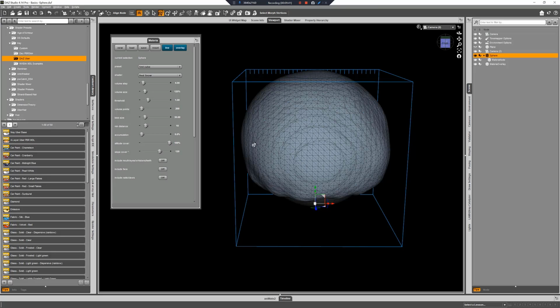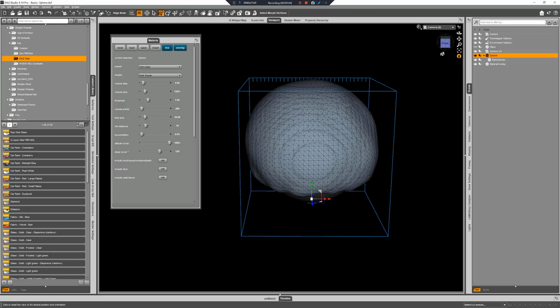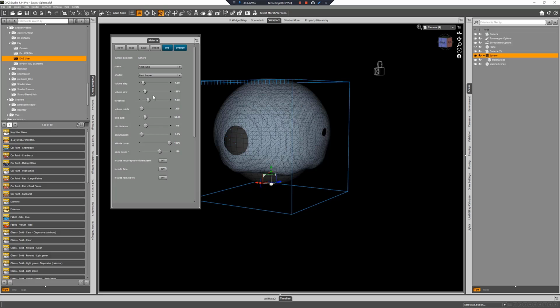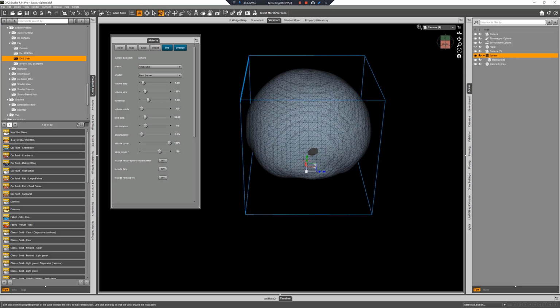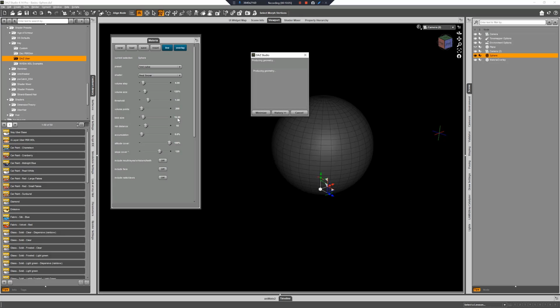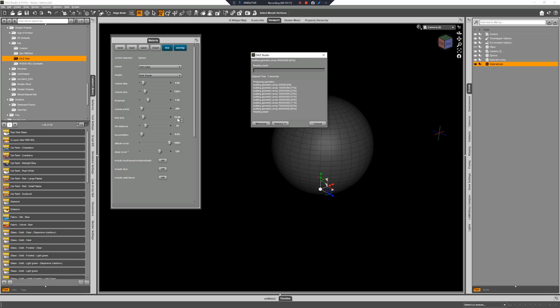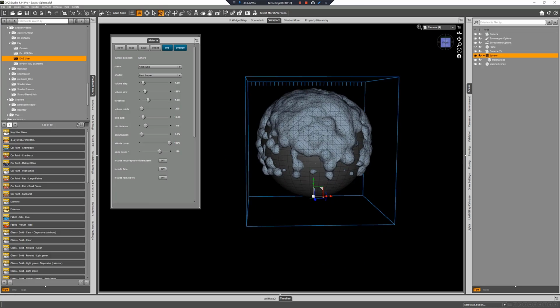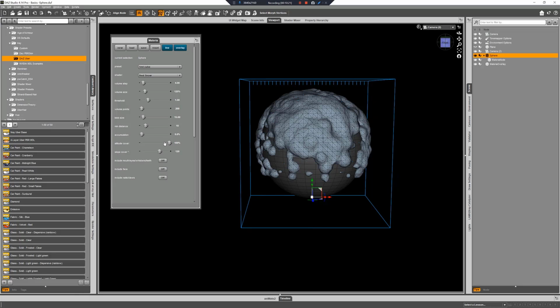So this is the geometry that we generated, because the particles, the blobs, are so large that they are basically going to be very uniform in their output. And as you can see, we also have some of our geometry being cropped when it reaches the volume boundaries, which you can fix by increasing the volume size, or better, reducing the blob size. So reducing the blob size, we get much more definition for our geometry, and I think this is a much better look. But of course, that depends on what you need to achieve.